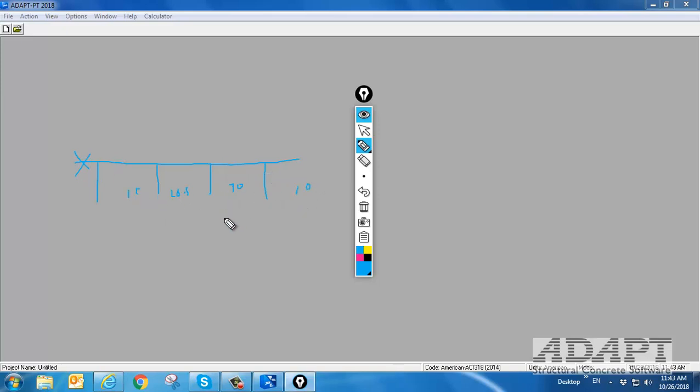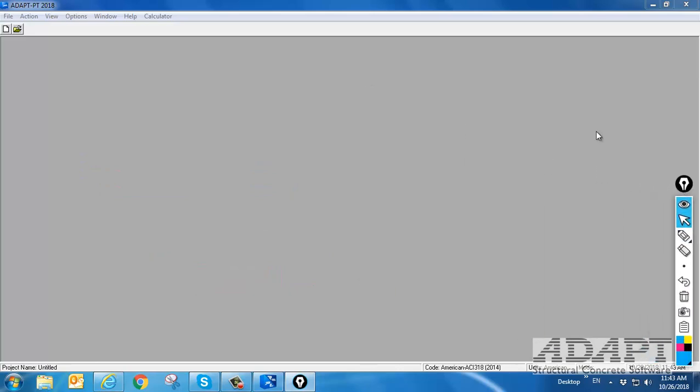In this span, if we look at a top view, we have a section that kind of looks like this. So this is the center line of the system, and then we basically have an opening here. So this dimension here will be 260 inches, and we're going to look at a 7-inch slab. Okay, so we'll model this. Let's go ahead and I'll delete that and then move this over to the side.